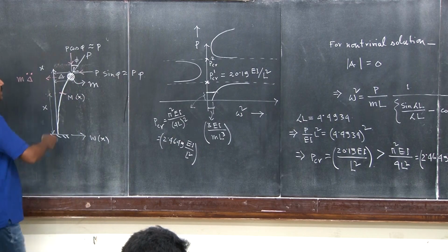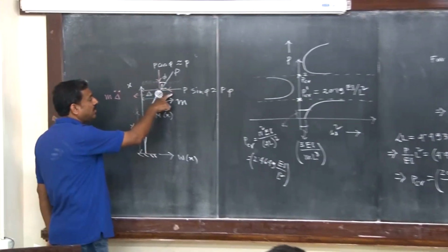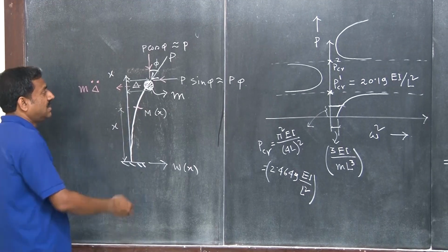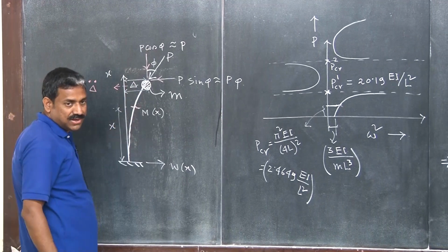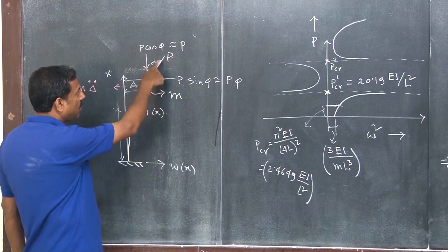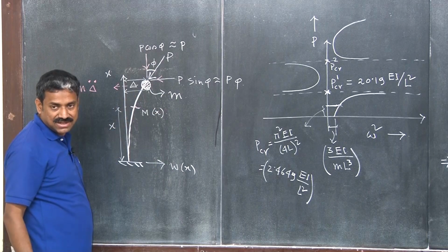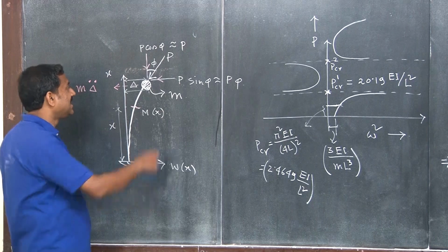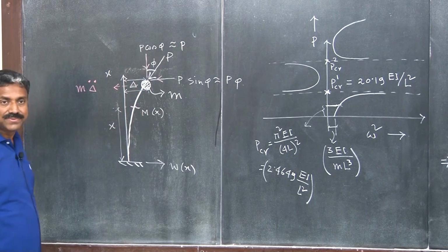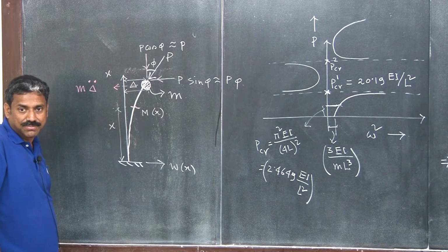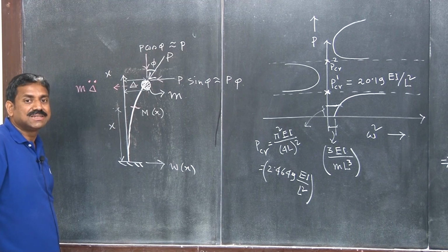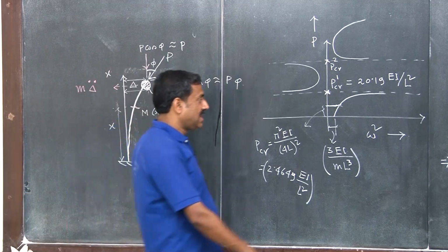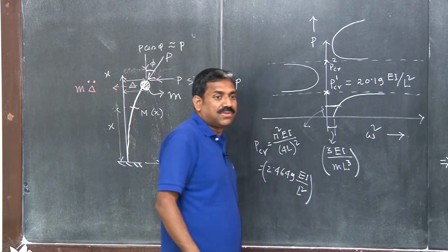You see, when it is a vertically compressing load, the component is basically a destabilizing moment, right? But for a follower force, the component of this is stabilizing. You see that, right? And so is the inertia. So the inertia and the component of the follower force have a stabilizing effect on the column. That is what enhances the critical load for instability under follower force, and that leads to a 10 times increase in the critical load.